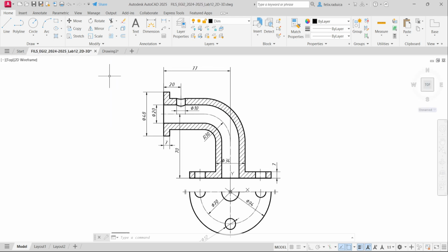And I also have this hole here. So I need to create a geometry which will be outside, actually inside geometry, which will be subtracted from the outside to make the hole. So I need a cylindrical body that will start from the axis line here and will go towards the top, intersecting the existing geometry and going outside. The dimension here, the height of this cylinder doesn't matter as long as it surpasses this part here.